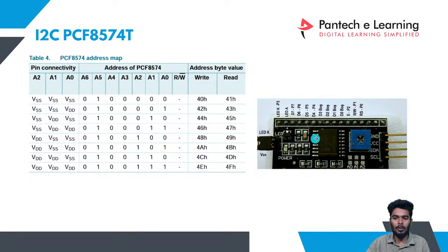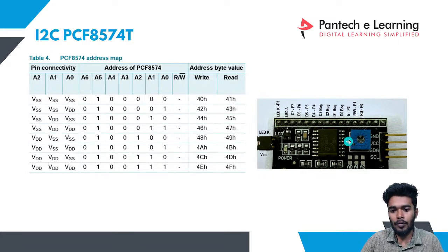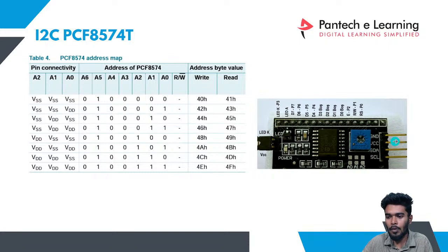You can commonly see this module with the LCD. Nowadays for Arduino I2C LCD, in Arduino we have an I2C library for LCD. All the LCDs will be interfaced with this module. So what is the use of this module? There is a difference between an I2C LCD and a normal LCD. With a normal LCD, we have to connect 20 pins to the LCD, and we have to give the instructions bitwise, sending logic 1 as per the requirement, depending on what you have to display. When you use this module between the STM controller and the LCD, you can use just 4 pins to send the data to the LCD. That is the advantage of this module. By using this module, we can use the LCD with just 2 pins, SDA and SCL, which come under the I2C communication.